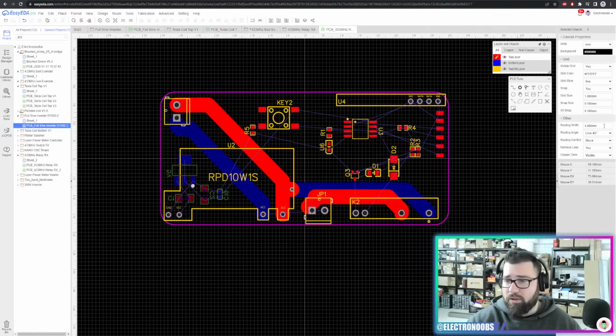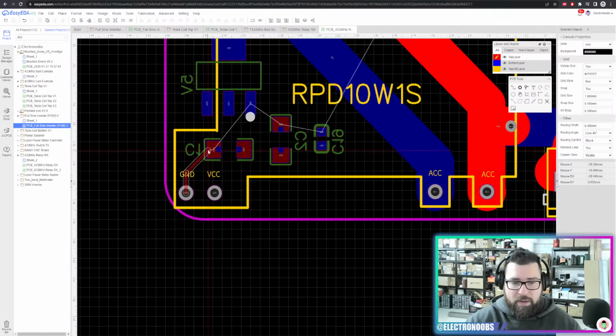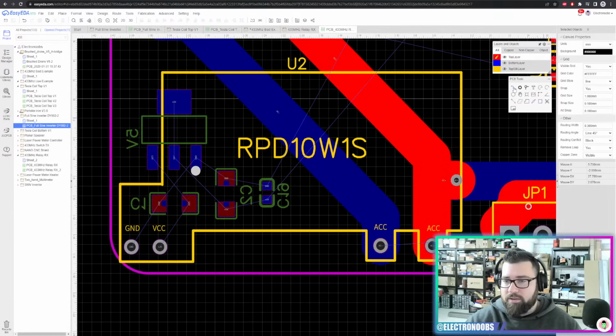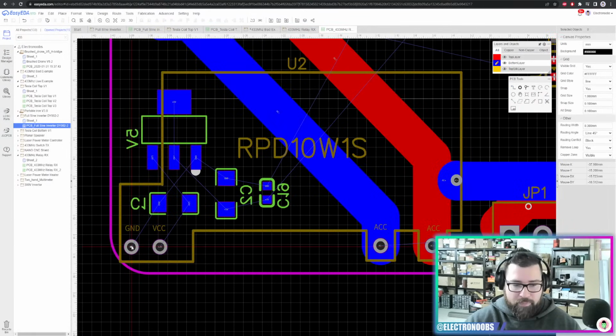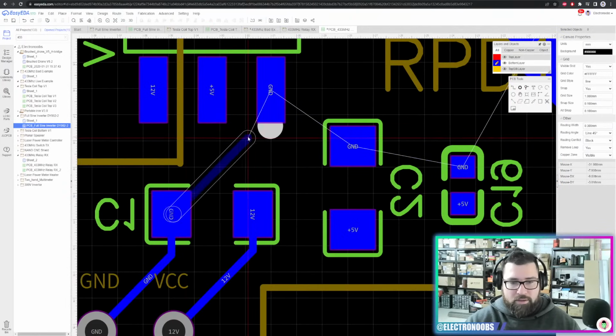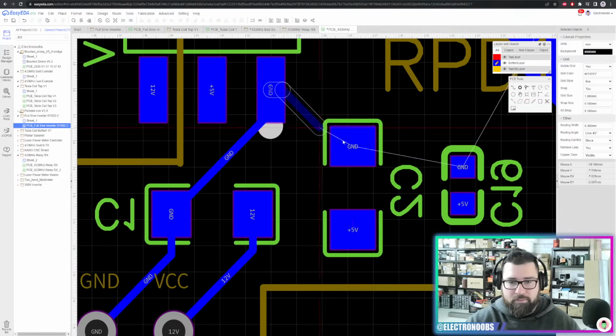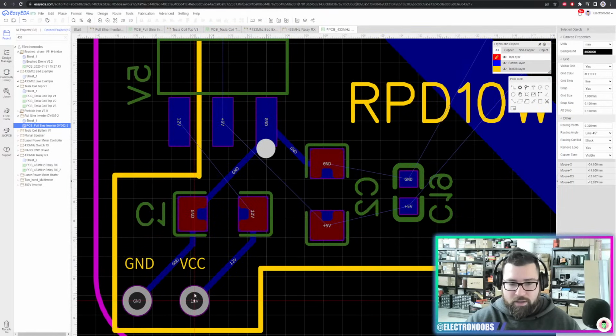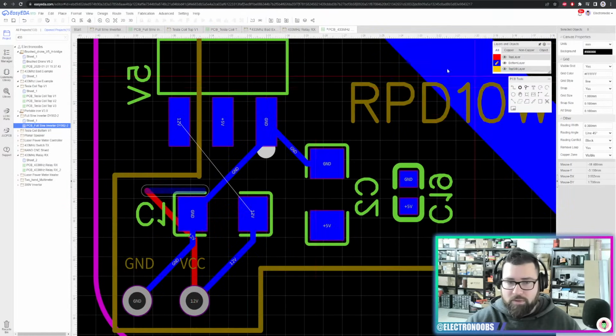And now we can go to the low power connection, which will be 0.3 in my case. 0.3mm is more than enough. And we start just routing manually. And as you can see, I've selected the position of the component, so this will be very easy to make. So just select the bottom layer here, connect to the PCB, to the capacitor, voltage regulator. This is the ground connection, ground here. Okay, for this we should make a top connection like this. Then we pass to the bottom side.